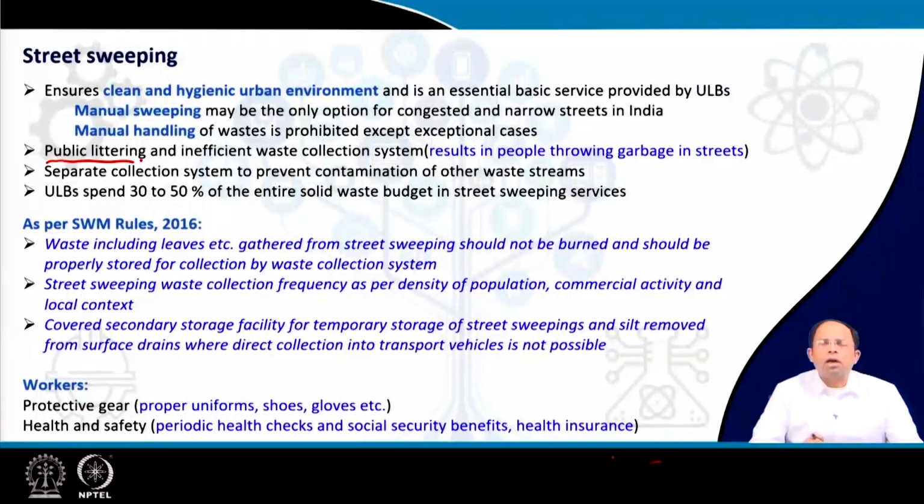For example, residences or maybe some institutions, if we are collecting waste, we will categorize those wastes into dry waste, wet waste, or even hazardous waste, and then we will transport them to the respective recycling centers or processing centers, or to compost plants, or to the landfill site, based on the waste stream's characteristics. Now, for this waste stream, we have to make sure that street sweeping waste doesn't mix with the other waste streams, because usually this waste contains a lot of contaminants, including heavy metals, and if that gets mixed with the other waste, it will contaminate those wastes as well.